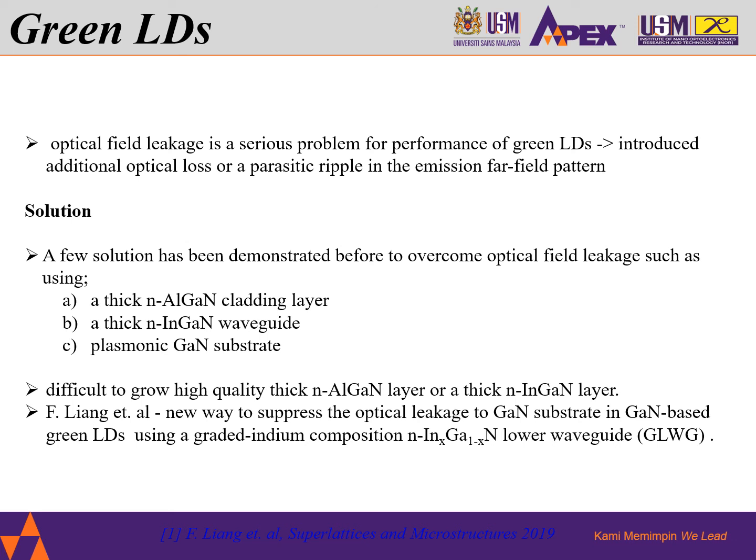A few solutions have been demonstrated before to overcome optical field leakage, such as using a thick AlGaN cladding layer, a thick InGaN waveguide, and also a plasmonic GaN substrate. However, it is difficult to grow a high-quality thick AlGaN layer or a thick InGaN layer.